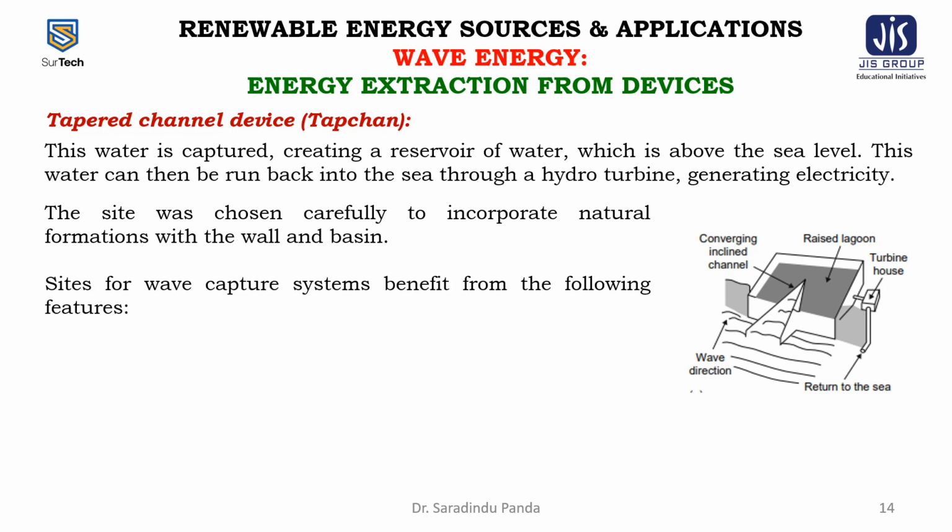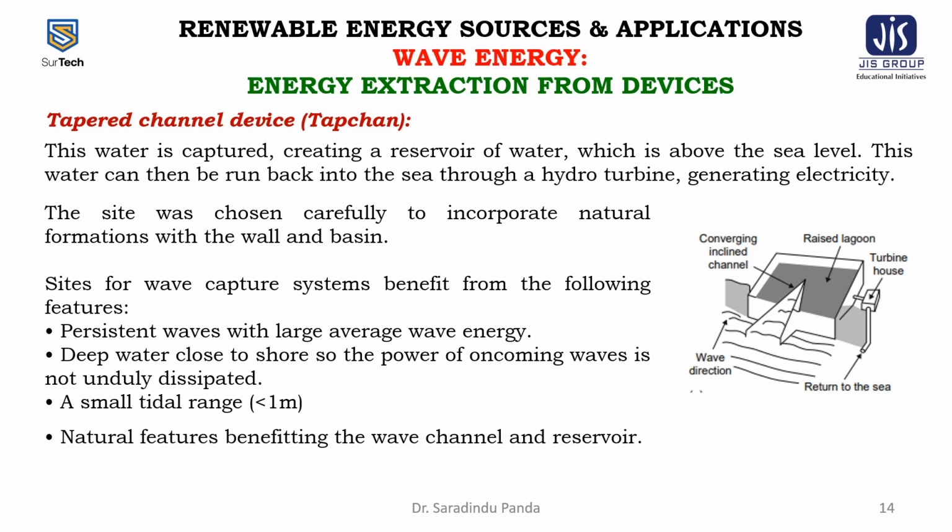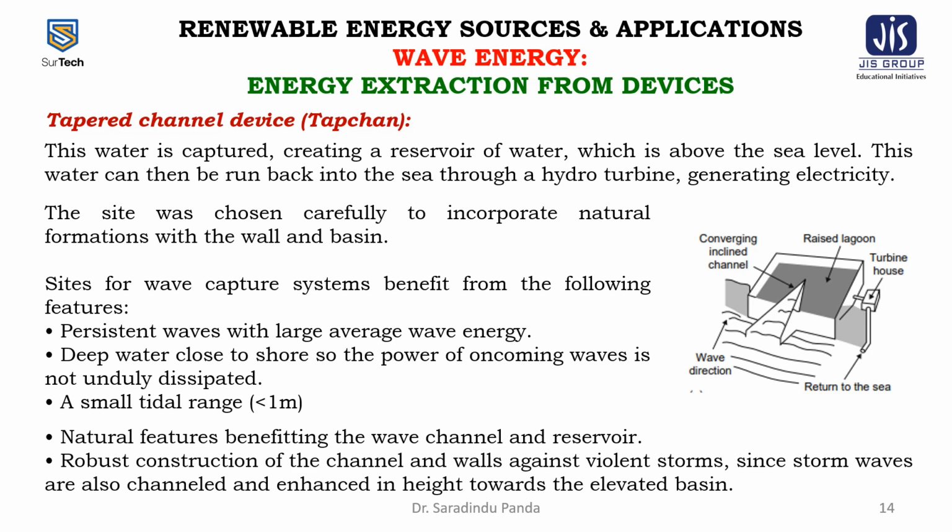Sites for wave capture systems benefit from the following features: persistent waves with large average wave energy; deep water close to the shore so the power of the oncoming waves is not unduly dissipated; a small tidal range, less than 1 meter; natural features benefiting the wave channel and the reservoir; and robust construction of the channel and the walls against violent storms, since the storm waves are also channeled and enhanced in height towards the elevated basin.